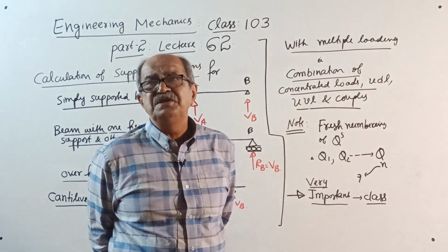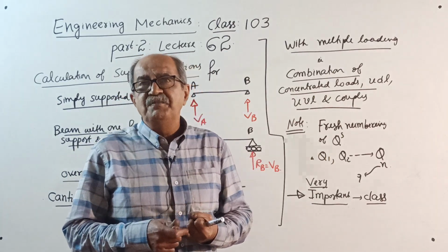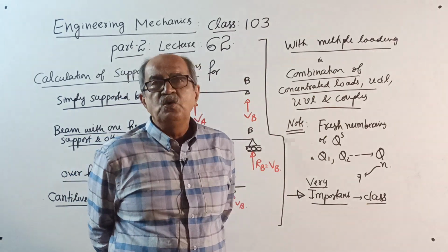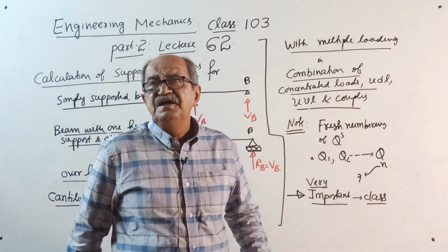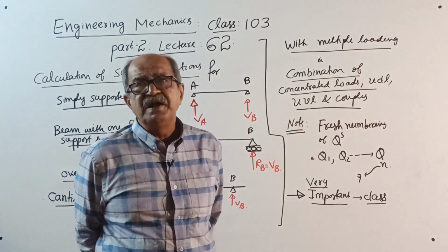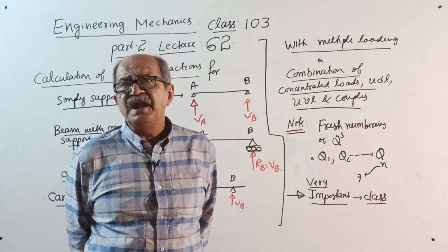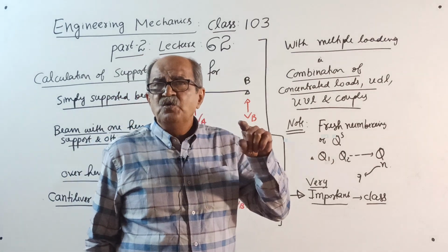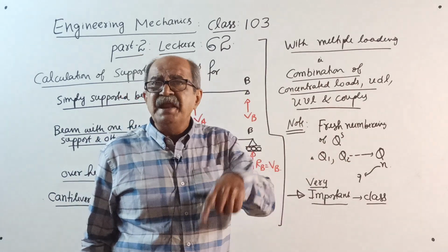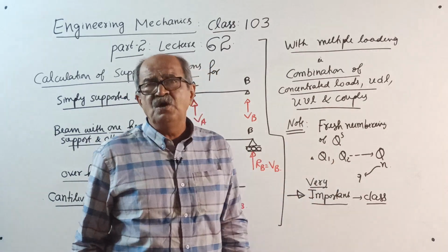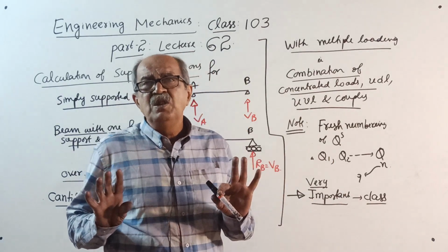Calculation of support reactions is a very critical part in structural analysis. If you want to draw SFD and BMD later, or when you go to statically indeterminate structure analysis, you require support reactions. If it is a statically determinate structure, you can find support reactions using basic conditions of static equilibrium. But if it is a statically indeterminate structure, you have to go for some methods that reduce the indeterminate structure to a determinate state. Then again apply basic conditions of static equilibrium. Right now I will not tell more.